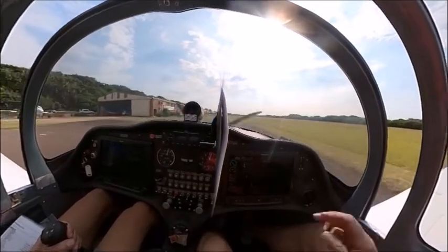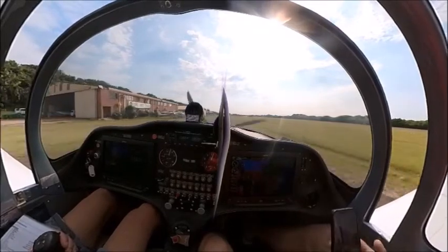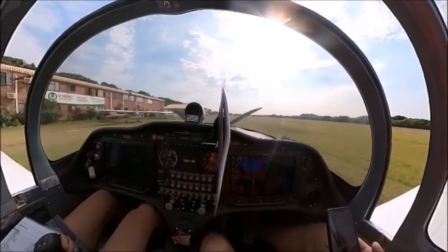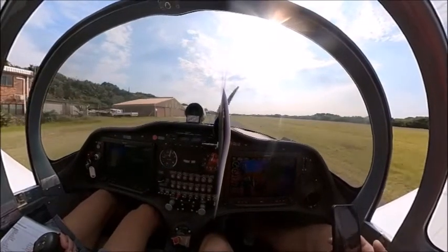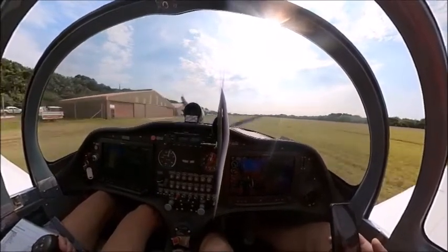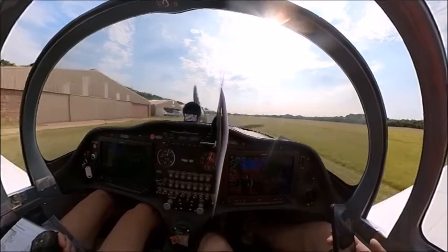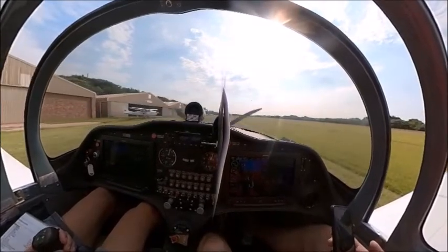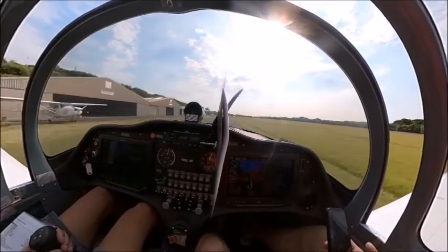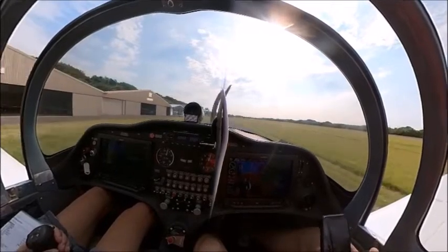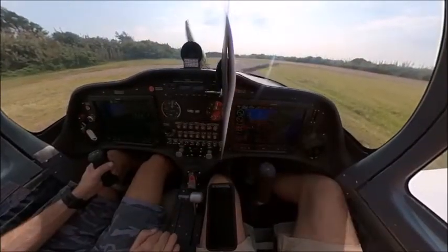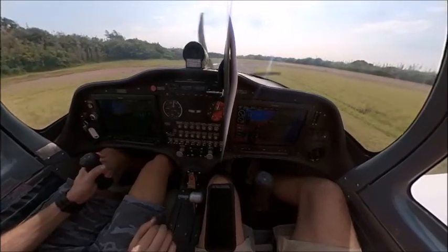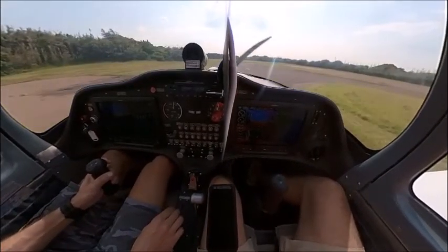Runways are numbered with 2 numbers, so in this case it's 23. That would stand for it going in a direction of 230 degrees. And the opposite direction will be 180 degrees from that. So in this case, 230 degrees minus 180 degrees would give you 50 degrees, and that would be for runway 05. So it's always looking at at least the first 2 numbers of the runway.